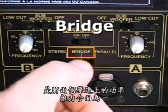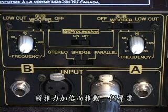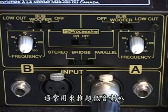3. Bridge mode, where each channel's power is combined into one giant mono output, effectively doubling the power being delivered to a single set of outputs. This mode is generally used for subwoofers and large speaker systems.